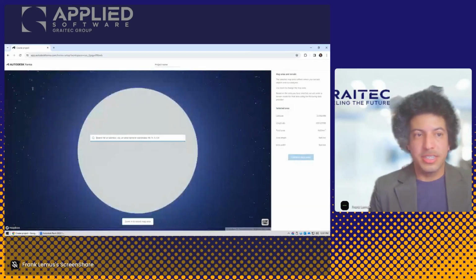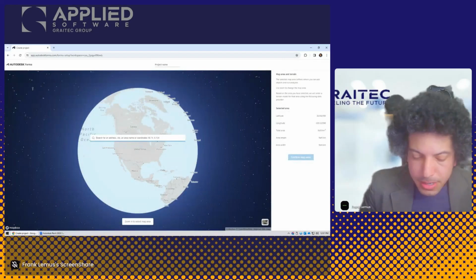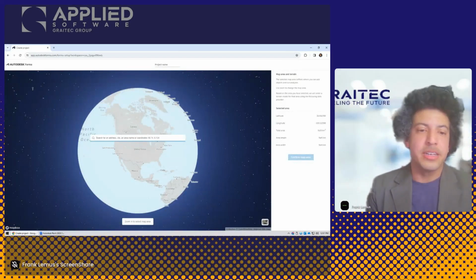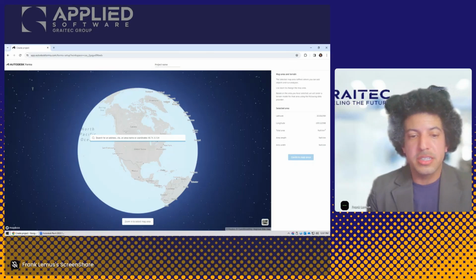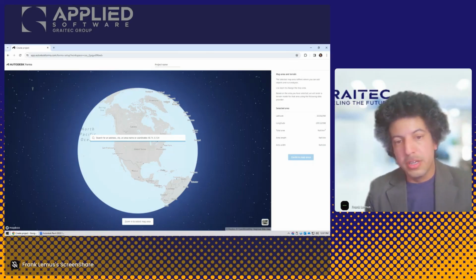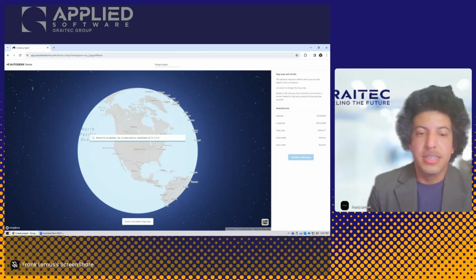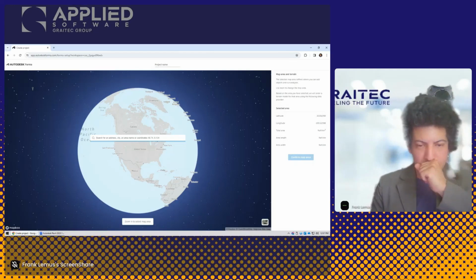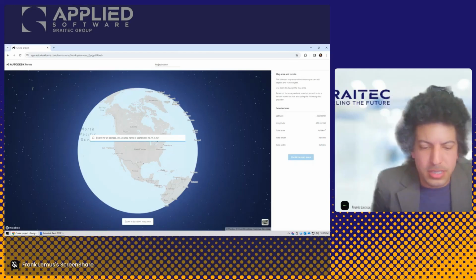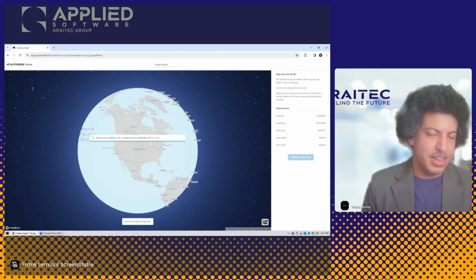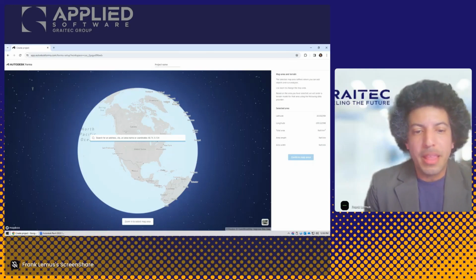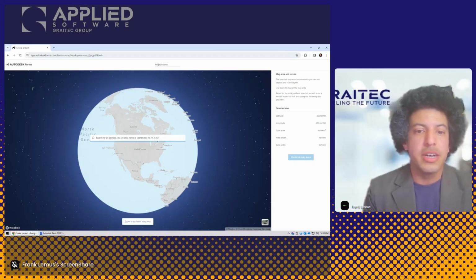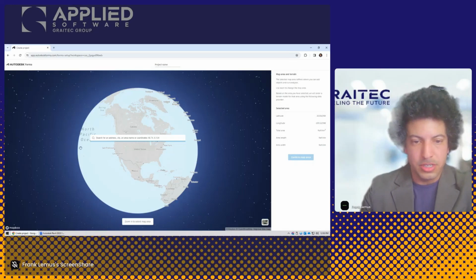So I'm going to click on that new project button. And Forma is all about analytical information. So naturally, the very first thing it wants to know is the location of your project, because it actually takes into consideration the location on the globe to do things like sun analysis and things like that. For things like wind analysis, there's ways to make modifications to those things. It's not so realistic that it's going to know the winds specifically for a particular location. And for the sun, however, it does know that location, of course, latitude, longitude, and all of that sort of thing.